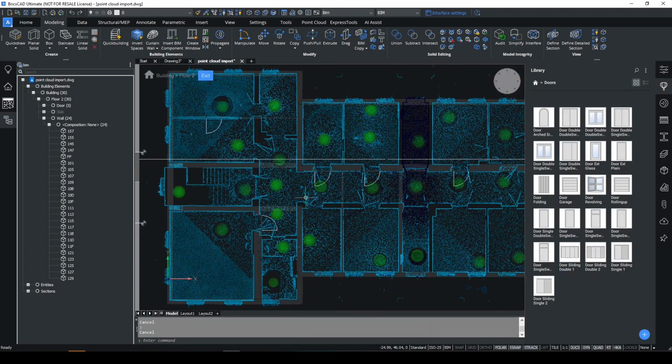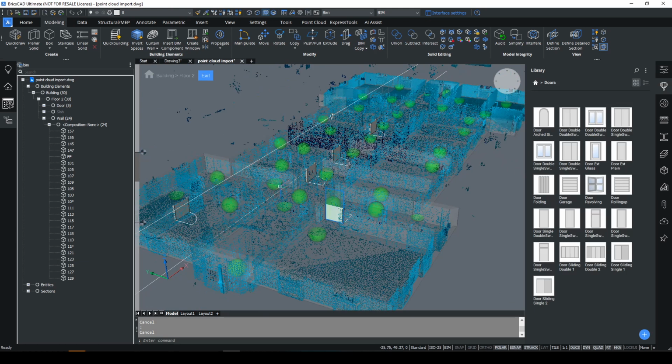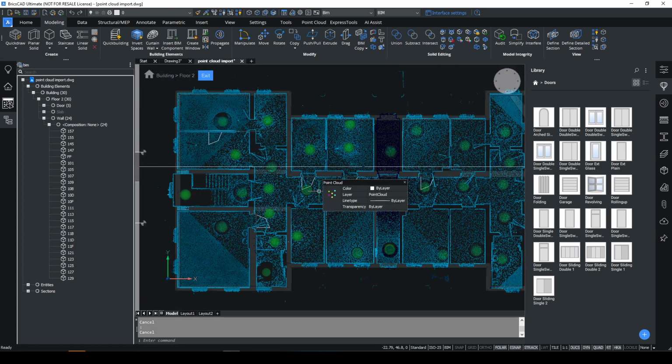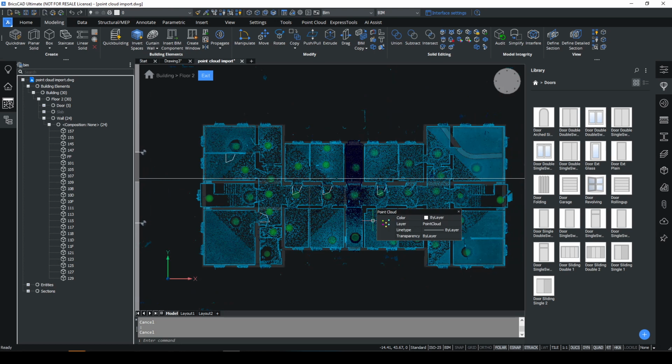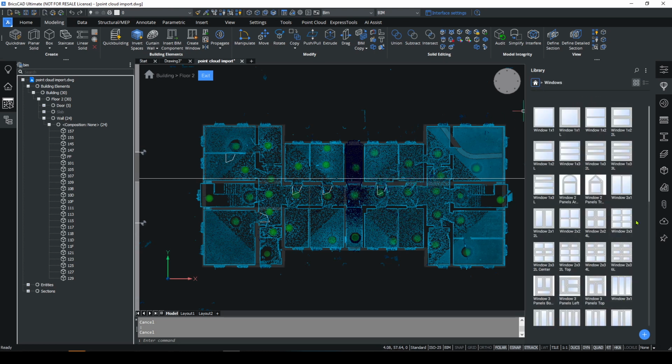Okay, and if we go to our 3D view, we can see we're actually drawing the IFC model still here, but we're fundamentally doing all this in the 2D view. So that takes care of the door situation. You'd obviously do a lot more of these and do it in a lot more detail. The next thing that we would do is go and put some windows in. So for the windows, same process. We will go and click on the window option here, pick the window type,